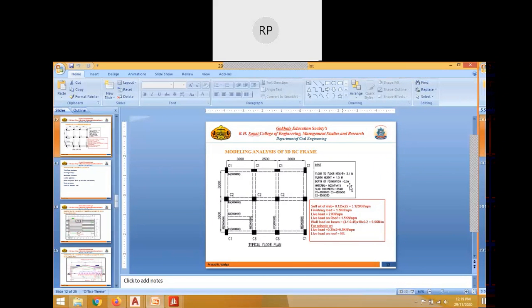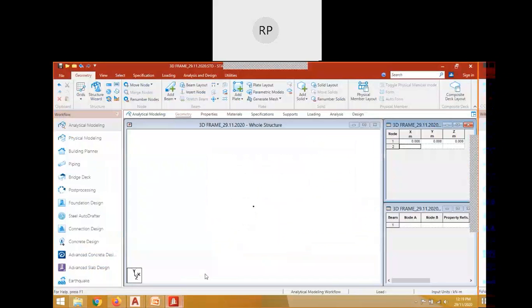So here you can see this is 1.5 meter as a plinth height and 2.5 meter as a depth of foundation. If you add these two, you will get 4 meter, right? So 4 meter is my next node that I want to create. The coordinate of that particular node is 0. Y is up positive, so I will put 4 here and then again a 0, right? Z is 0. So this is my first node.